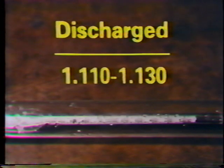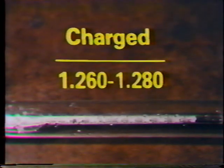When you use a hydrometer, be careful not to draw in too much liquid. If you do, the float may hit the top of the tube and you'll get a false reading. Now, this tube doesn't have too much liquid in it. As you can see, the float sinks to a certain level inside the barrel. The level of the float indicates the specific gravity of the electrolyte. If the cell is discharged, the scale on the float will read between 1.110 and 1.130 for most lead-acid batteries. If the cell is charged, the scale will probably read between 1.260 and 1.280.